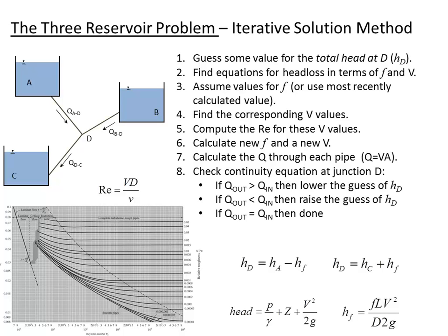We would probably use just 0.02 for our first guess on the 12-inch pipe, and then for the galvanized iron, 7.5 times 10 to the minus fourth, that would be a little bit lower. We'll use 0.019. All right, so we'll keep that in the back of our heads as these initial values of F that we're going to use in step 3 of this process.